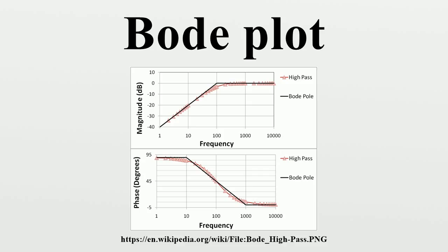This section illustrates that a Bode plot is a visualization of the frequency response of a system. Consider a linear, time-invariant system with transfer function. Assume that the system is subject to a sinusoidal input with frequency that is applied persistently, i.e., from a time in the far past to a time in the far future. The response will be of the form, i.e., also a sinusoidal signal with amplitude shifted in phase with respect to the input by a phase.